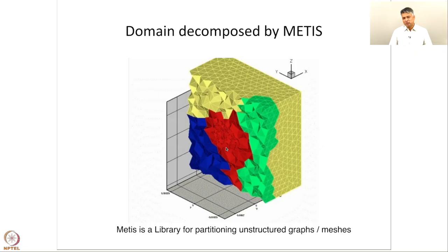So when we have to distribute this problem, if we were to take a simple geometric approach where we just divided it based on Cartesian methods, like applying slices of planes in the x, y, or z direction, we will end up with a very uneven distribution of cells. You will have a lot more cells towards the center of these partitions and fewer cells in subdomains which are away from it. That would result in a fairly uneven computing load, which would result in very varied timing, and you will get terrible performance.